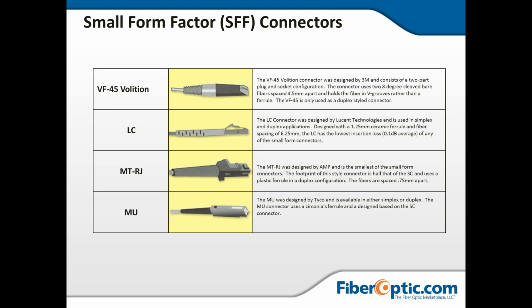Don't see it as often overseas and international. The MU, as I said before, Japan and China, the Pacific Rim, very popular over there. The MU was designed by Tyco and is available in either simplex or duplex. The MU uses a zirconium ferrule and was designed based on the SC connector. So bigger, not always better.